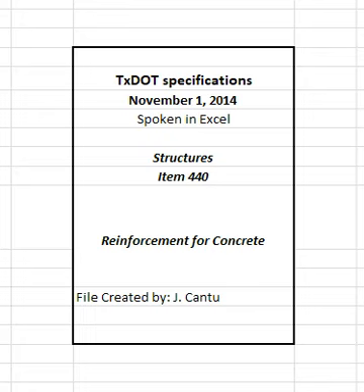Provide steel conforming to ASTM A615 or meet the physical requirements of ASTM A36 for smooth bars that are larger than number 3. Designate smooth bars by size number up to number 4 and by diameter in inches above number 4. 2.4 Spiral reinforcement.